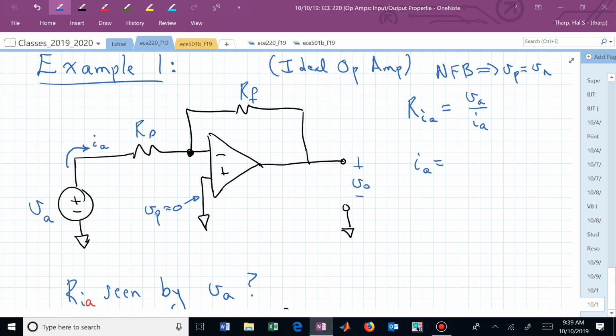And that's a reasonable thought, and why are you making that? Because it's kind of connected to the inverting pin of our op-amp, right? And we said the input impedance of these op-amps are really, really big, and consequently then the current going in, so we can say that here, I sub P is equal to 0.